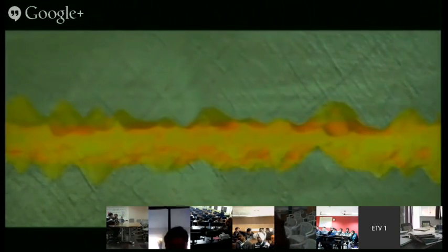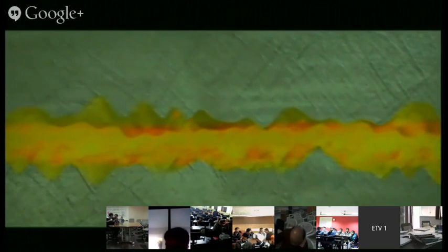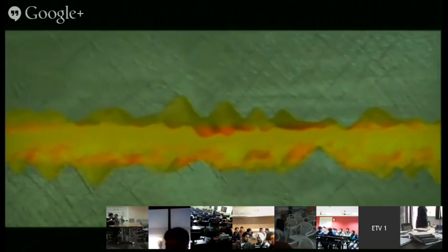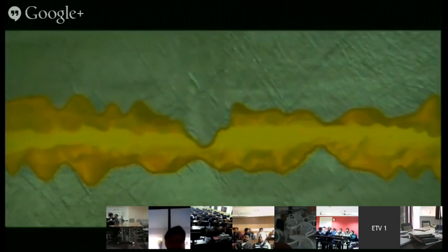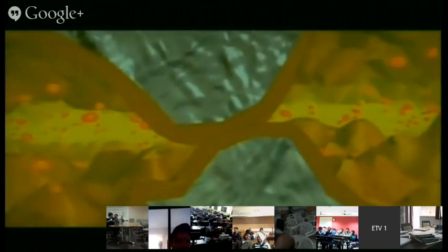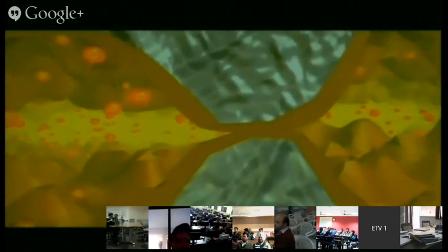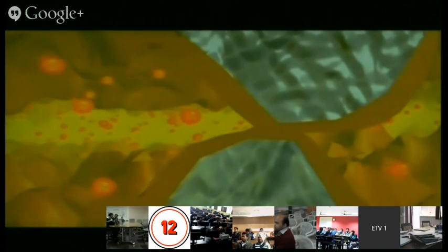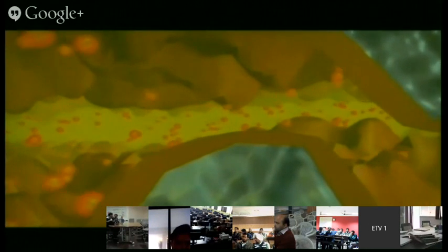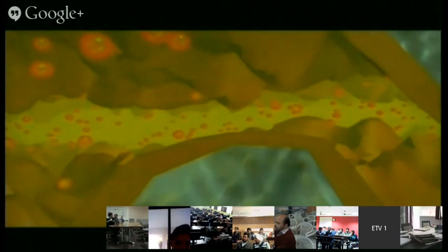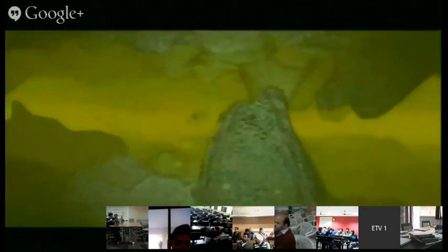Now, if viscosity is very low, then the chances of metallic contact, asperity to asperity contact, will be high. In that situation, additives are normally used in the lubricant, and these additives react over the surface and a monolayer of the additive is formed. Once asperity contact occurs, this layer protects against metallic contact and friction will be lesser. So this is the theme, how friction comes into the picture between the cylinder liner and piston ring.